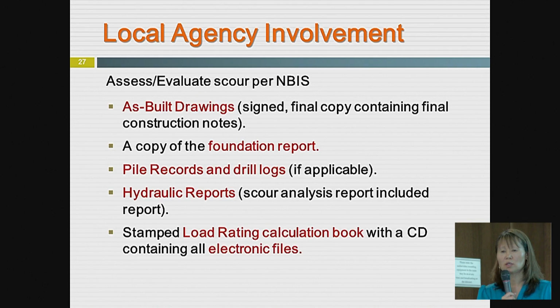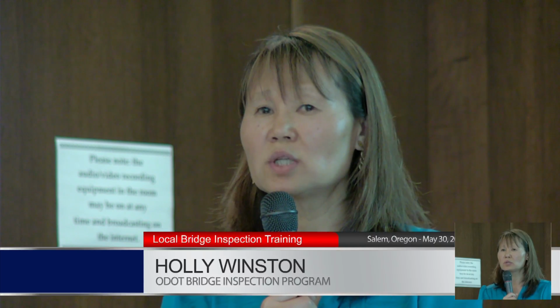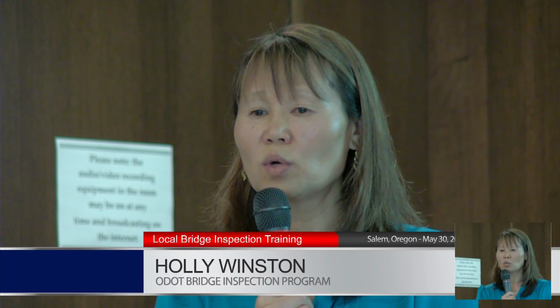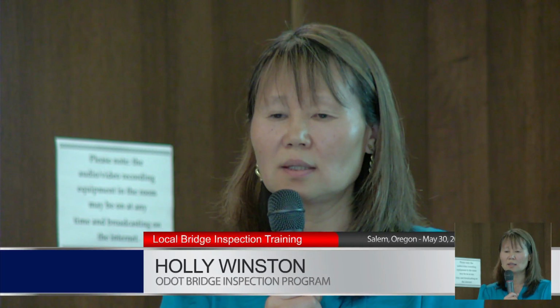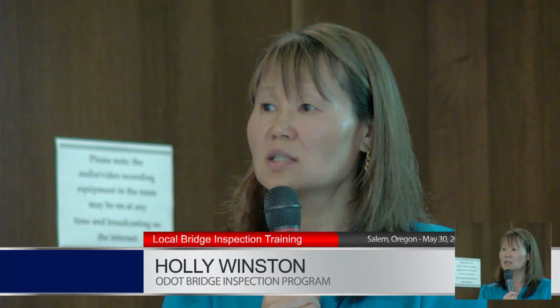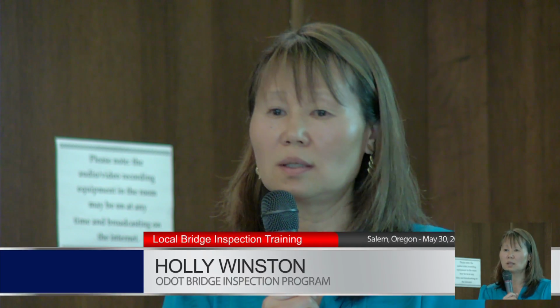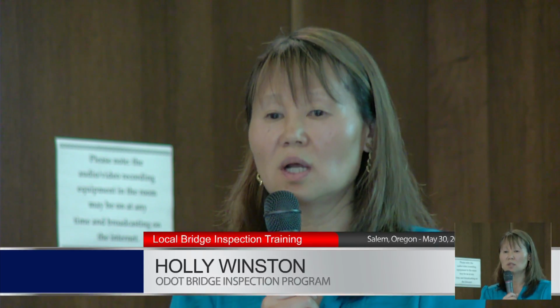So I just want to let you know what I require. I just want to go over it again. I need the as-built plans to see what was built, and then of course we need the foundation report. That's one of the main reasons a bridge becomes unknown, because we have no record of what's built, and the inspector can't see, none of us can see. We haven't developed that Scour yet, unless we spend an extensive amount doing probing, non-destructive.